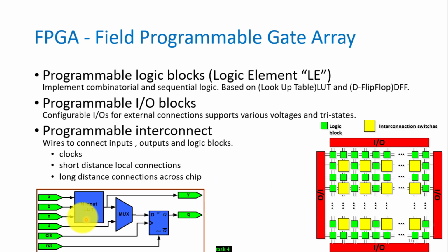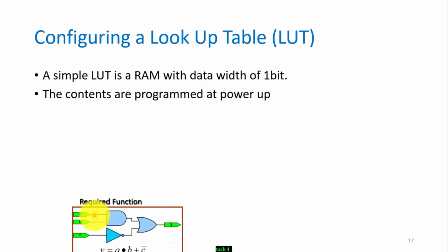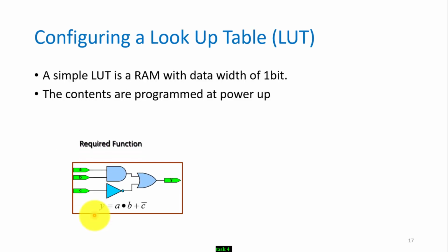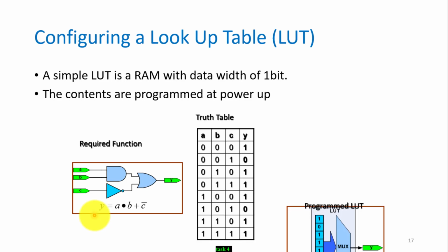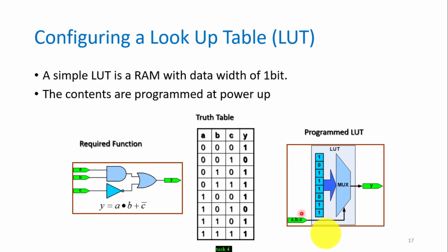So what you have to do is get the lookup table. What's a lookup table? Instead of building the logical function, we create a lookup table for that function. Just a decoder that will have the inputs already there, or a multiplexer, once we choose something, we get the output instead of doing the logical circuit.